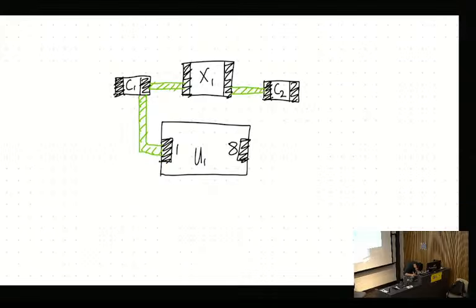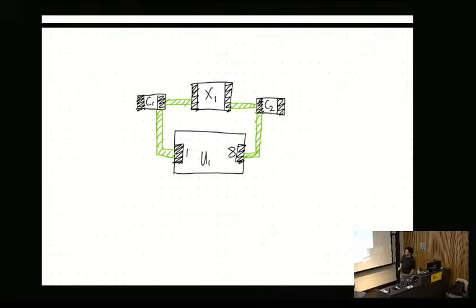And so I've now got my signal. This is just the top layer of the PCB. You can see I've minimized the trace length as much as possible, and you would write this in your paper: minimize the trace length. I don't have any weird corner interactions between different traces, so there's no parasitic capacitance there. I've also made sure the crystal is equidistant between both of them.